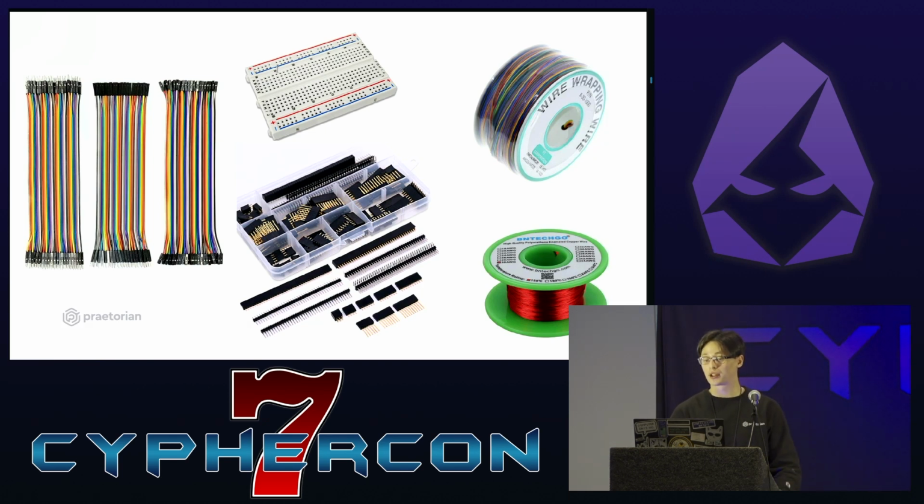At the top in the middle, that's a solderless breadboard. Those have little strips of metal on the inside that the wires can friction fit into, so you don't have to solder all these wires together. You can use that for temporary prototyping connections. You may also encounter cases where you have to make a voltage level translator, and just prototyping one on one of these little breadboards is very handy.